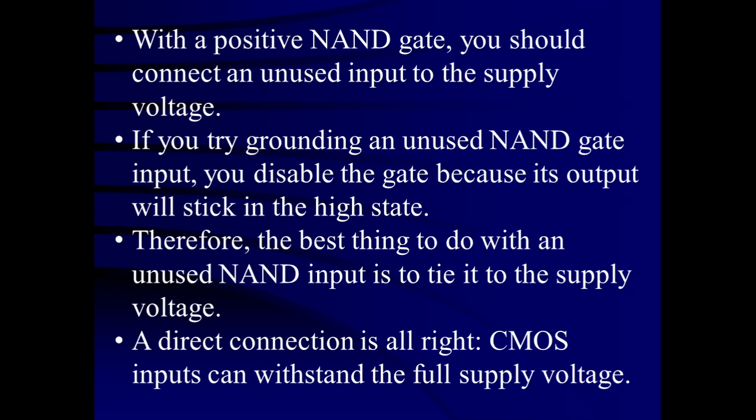Similarly, what happens to the positive NAND gate? Just like in a NOR gate, where any one input being high sticks the output low, in a NAND gate, if any one of the inputs is low, then its output is definitely high. That means only one input, if it is low, can control the total gate, and the rest of the inputs lose their control.